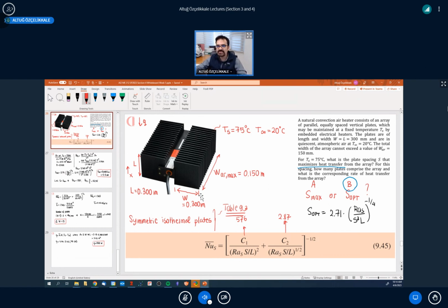Free convection, on the other hand, is quite maintenance free because you don't need to maintain a fan. You can attach this to power systems that are on the outside. They're not affected easily by the outside weather conditions, and still they are able to dissipate a decent amount of heat. You can see that 835 watts is quite decent. Okay, so any questions about the example problem?